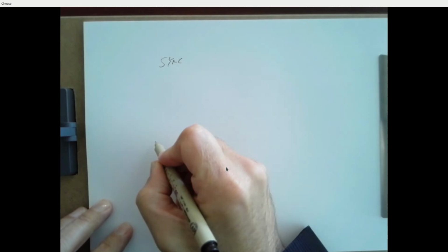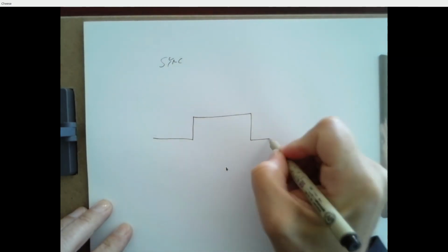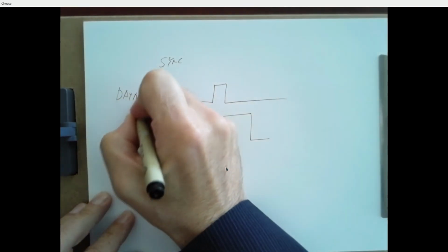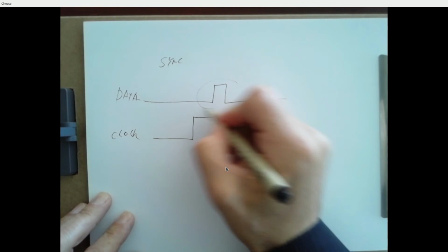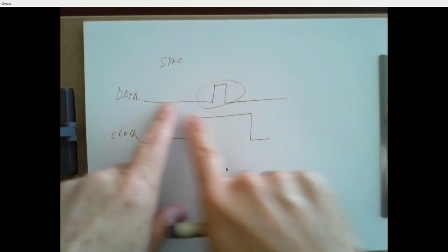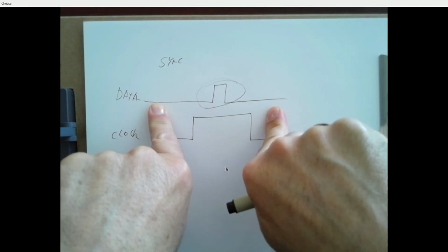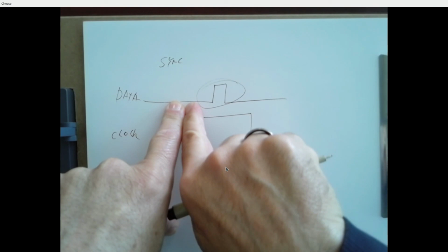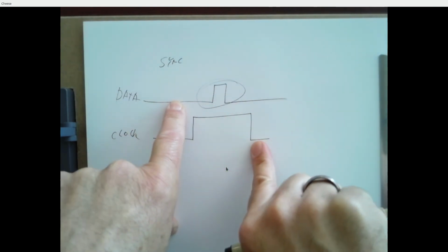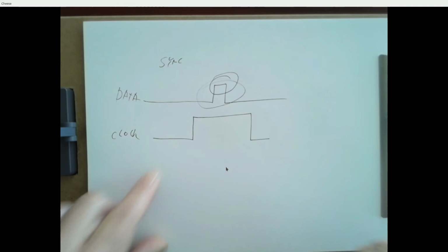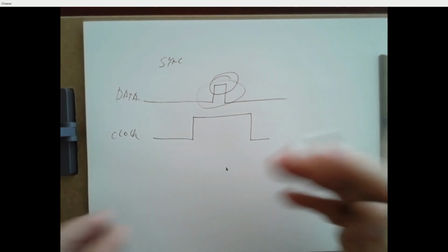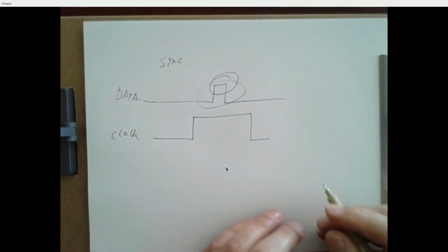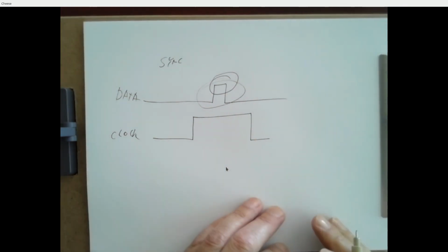And the way we do a sync pulse is raise the clock and then pulse the data. And this is normally not a valid thing to do, right? The data is supposed to be stable for the duration of the clock pulse. But if you see the clock line go high and the data line is low, keep sampling the data line until the clock drops. And if you notice a pulse in there, that's saying, I want to resynchronize. So whatever you're doing internally to build up your characters, reset your counters back to 0 so that the next valid bit becomes the least significant bit.